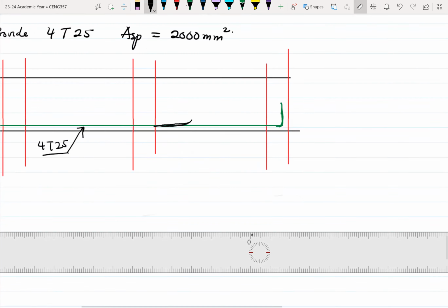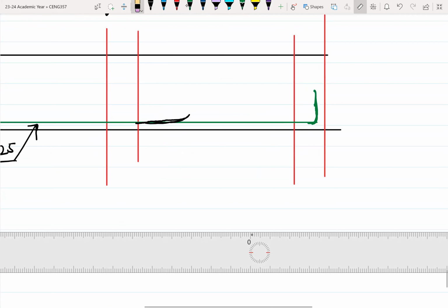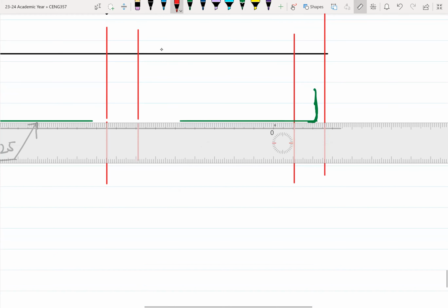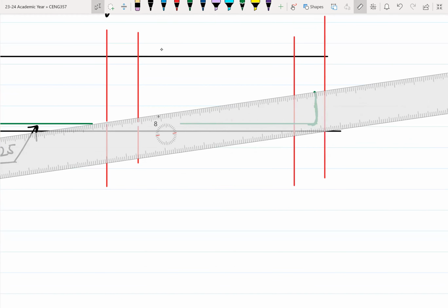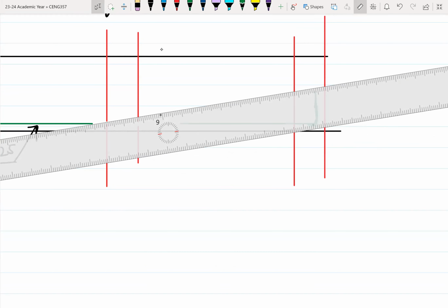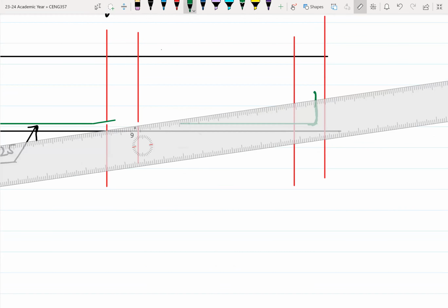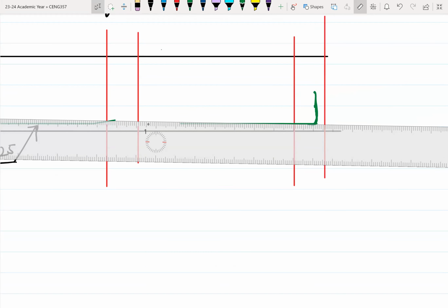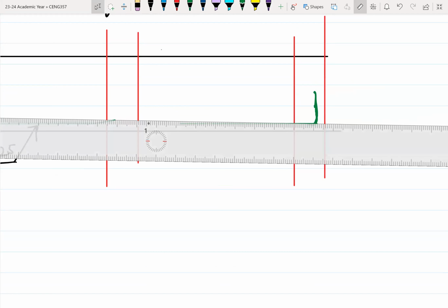All right. So to exaggerate that, sometimes when you take some drawings, you see this. Usually when you're lapping, you lap where its effect is not significant on the behavior. So usually for tension at the bottom, you lap closer to the support, right? So you have something like this. Okay.